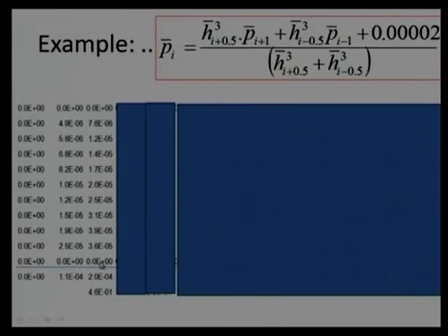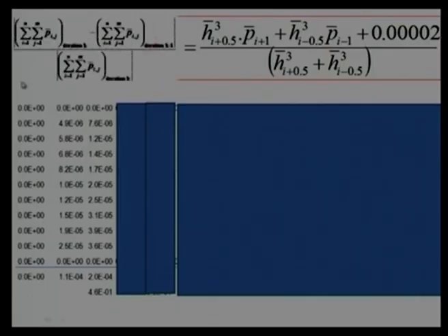Boundary condition is 0 here, 0 here, it is affecting the results, and that is required also, because we know the pressure profile in this kind of surface will be parabolic. Otherwise, it will not turn out to be parabolic, it will turn out to be some linear profile at the exit. And we can use this iteration loop.